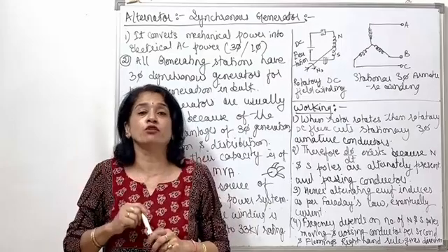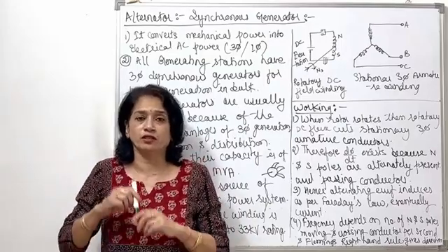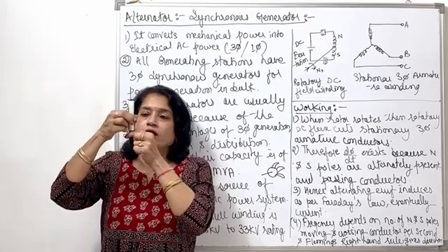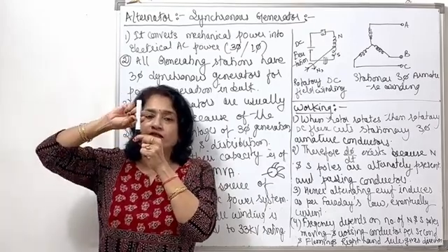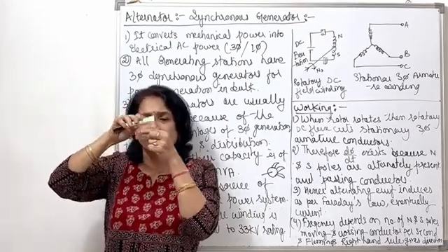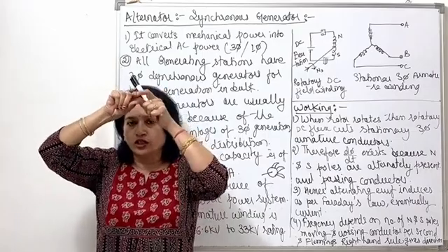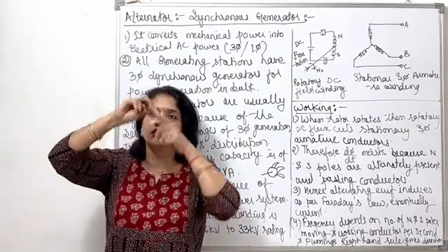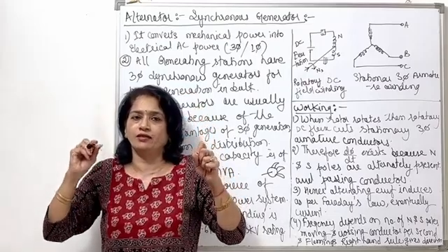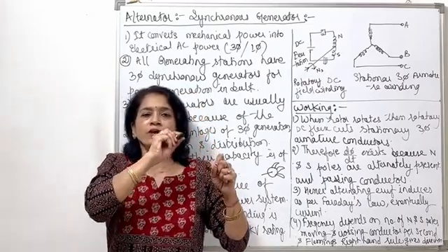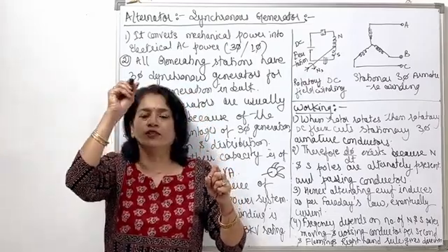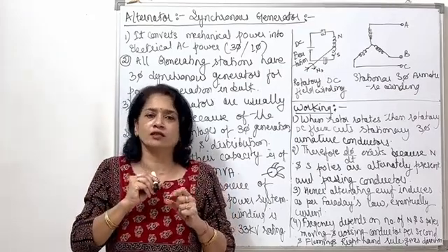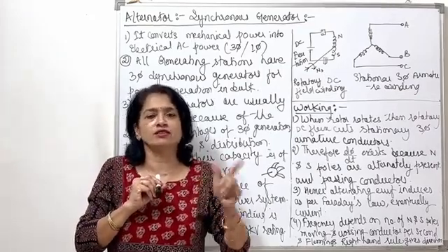That means the variation of flux is there with respect to these conductors, because in the physical structure, mechanically, the rotor's north and south poles are rotating like this. But outer to it, after the air gap, we have the stator periphery in which conductors are placed like this. In a circular periphery, we have the horizontal placement of the conductors. 36 conductors are there, 12 conductors each for A phase, B phase, and C phase.